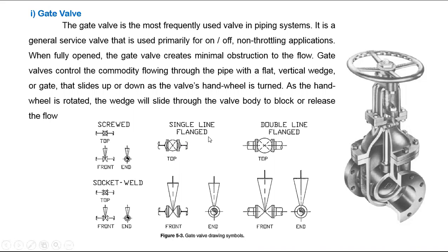Simply you don't draw the pipe. If you are drawing a double line pipe, everything will come into your mind because you are offsetting the pipe as per your pipe size. You can easily find it, but in a single line system it is very dangerous. You have to keep in mind the flange size and give space for it, and for maintenance purpose some gap you have to provide between both pipes or from the wall.